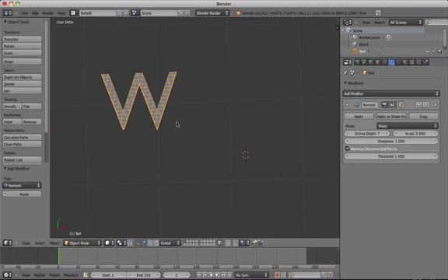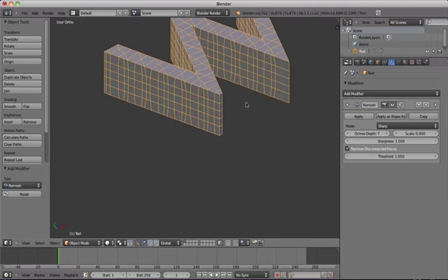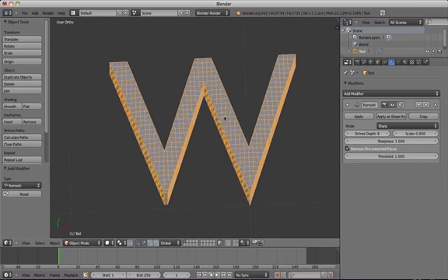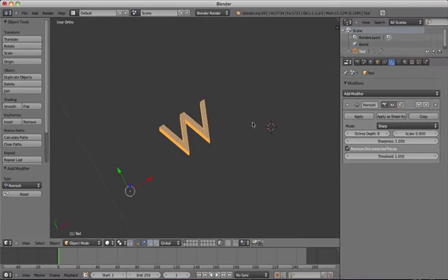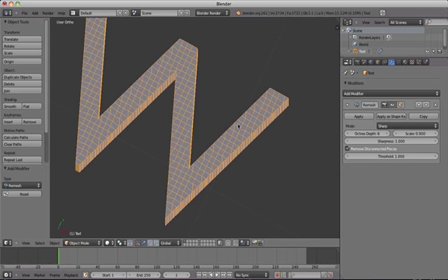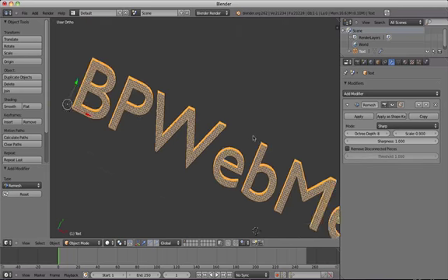When we added the Remesh modifier at that time, only one of the letters was left. This is because of the Remove Disconnected Pieces checkbox in the Remesh modifier options. If you untick this box, then the other letters should come back.